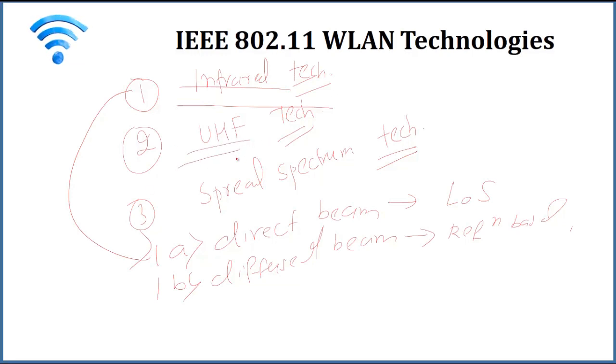So UHF is actually UHF narrowband technology. Whenever we write simply wireless technology, instead of just UHF technology, we will always consider UHF narrowband technology. Okay, so UHF wireless data communication systems have been available, I suppose, since the early 1980s. These systems normally transmit at 430 to 470 megahertz. So in that particular frequency range, with a rare system using segments of the 800 megahertz range.